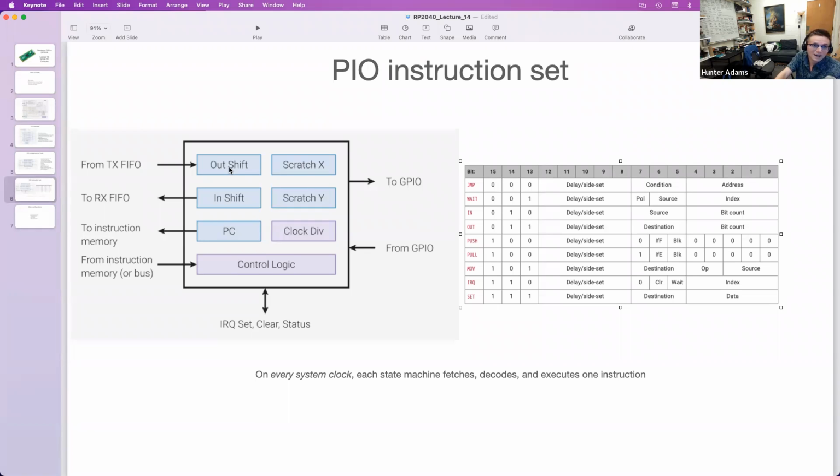So you could say, I am modifying the program counter with an out command. It might alternatively, and maybe we'll come to this, this is getting a little twisted, but you could say, I would like whatever data is contained in the output shift register to be executed as an instruction, right? So remember that.